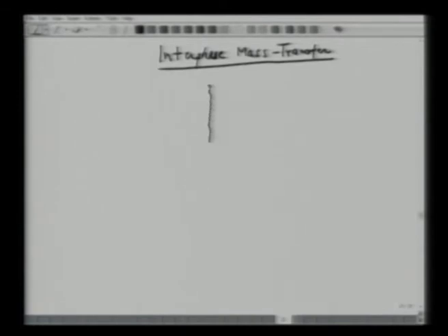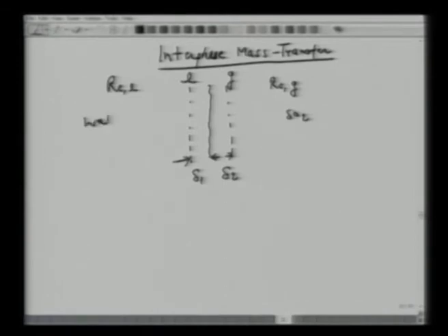So now if we say that we have two phases, liquid and gas, both have certain Reynolds numbers: we have the Reynolds number for the liquid, and we have the Reynolds number for the gas. Again we can now have two resistances, diffusion resistances, one in the liquid phase and one in the gas phase. So we can have del 1 and del 2. So two diffusion resistances. Suppose this is your sulfur dioxide, and this side we have water, and this sulfur dioxide diffuses across this interface.